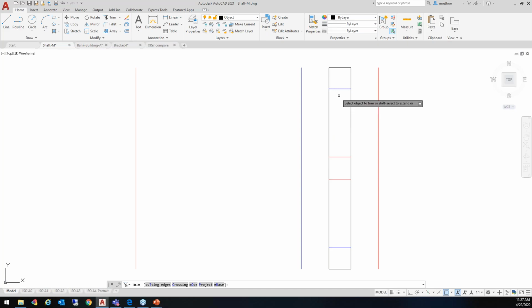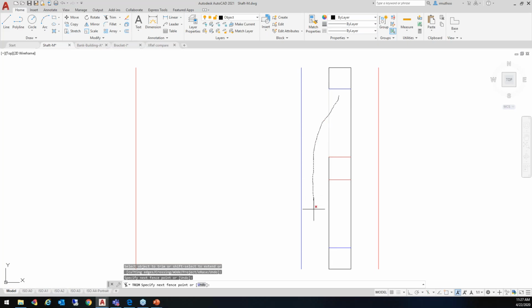So all I do is I start here and then keep on moving it over this, then come out and go down and then move it in here, then move it in here, and probably move it in here, and it will detect all the cutting edges, and it will also trim those 4 lines separately.